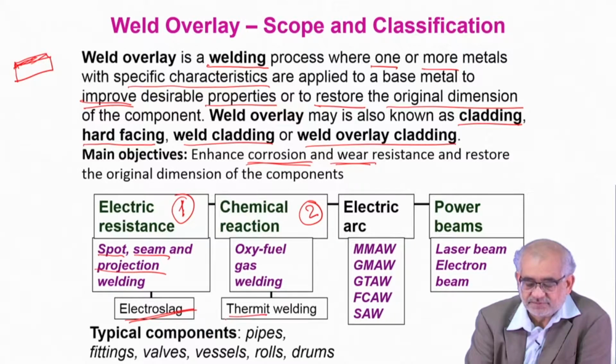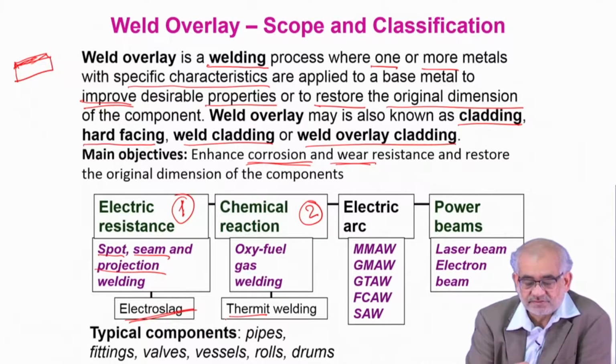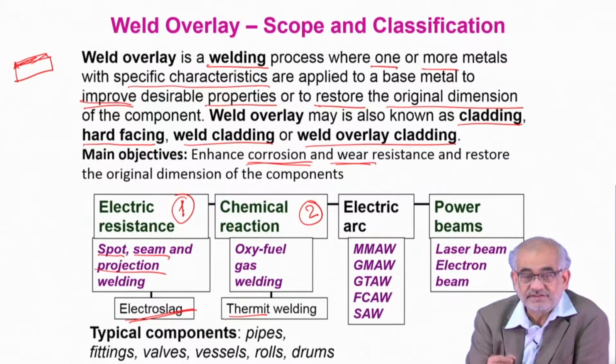So that's called thermit process. Say for example, in railways, this is very routinely used when you want to join two long strips of rails. You actually use a mixture of aluminum and iron oxide, and then you heat using the oxy-fuel torch, and aluminum reacts with iron oxide, substitutes Fe from Fe2O3, and in turn creates alumina, which is a slag phase.